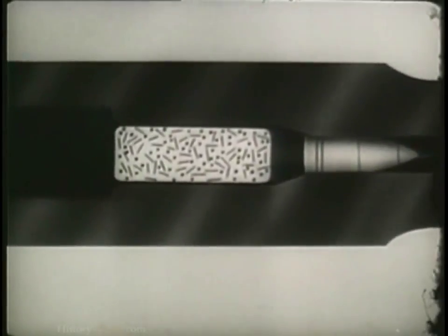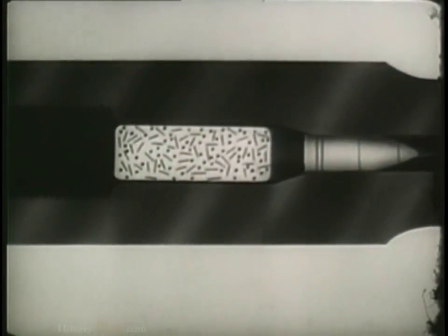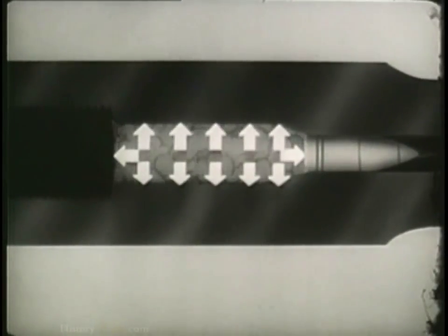In any gun, howitzer, mortar, or small arms weapon, the pressure behind the projectile is caused by the burning of the propelling charge or propellant, which forms a tremendous amount of gas in the chamber. This pressure is measured in thousands of pounds per square inch and is exerted equally on all surrounding surfaces, but with different results.